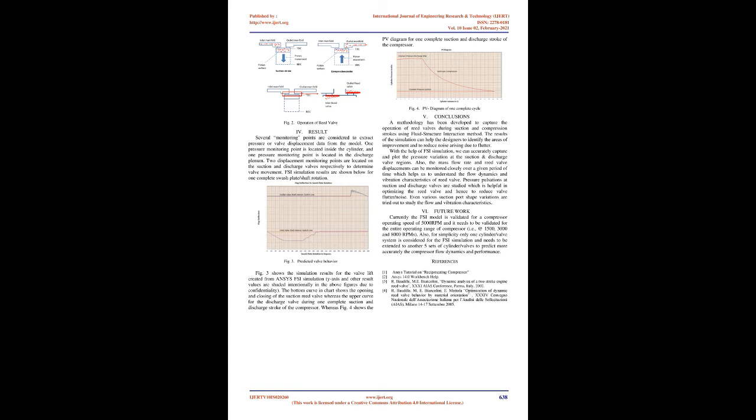Fig 3 shows the simulation results for the valve lift created from ANSYS FSI simulation. Y-axis and other result values are shaded intentionally in the above figures due to confidentiality. The bottom curve in the chart shows the opening and closing of the suction reed valve, whereas the upper curve is for the discharge valve during one complete suction and discharge stroke of the compressor. Whereas Fig 4 shows the PV diagram for one complete suction and discharge stroke of the compressor.